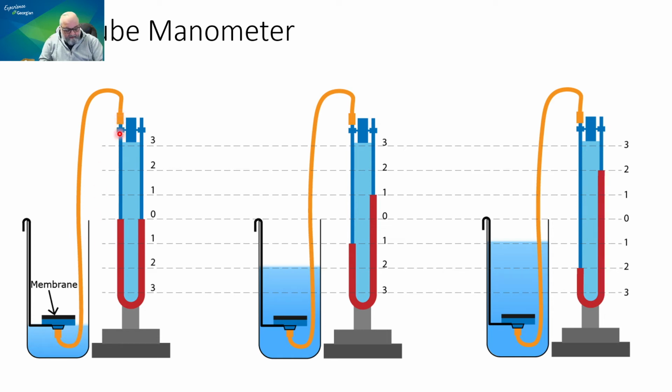So in this case, you can see that this U is a liquid, and the liquid is simply undisturbed. Now, if we keep adding water or other substances into this container, what will happen is this weight is going to push down, and it will simply disturb that U-shape liquid, and it will create two levels that are not even, and the difference between those two levels is the pressure you're reading here.